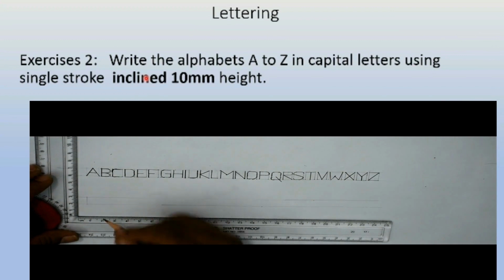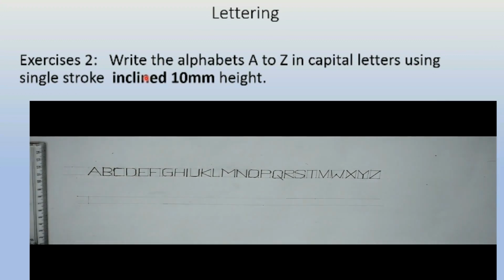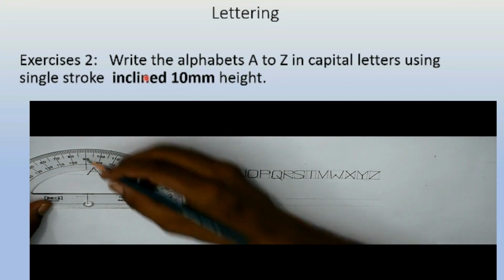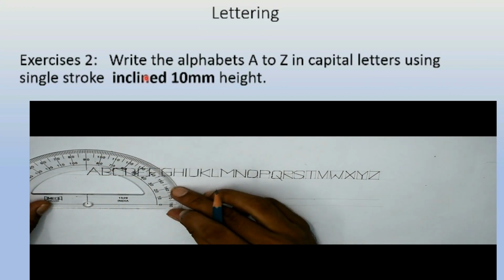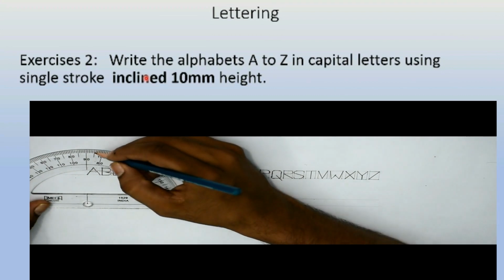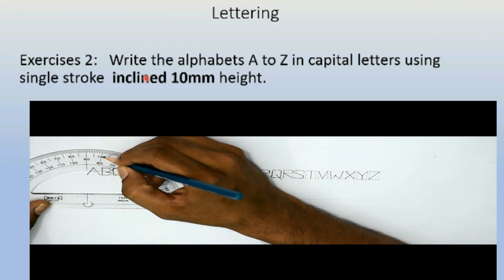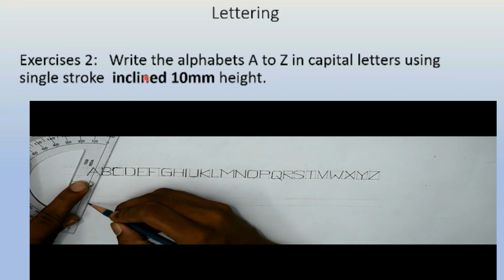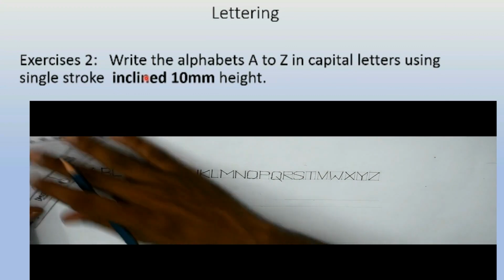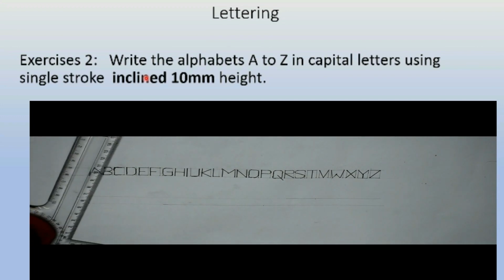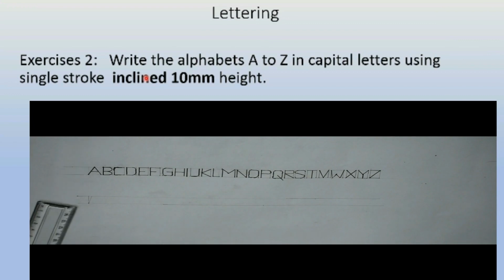Incline here with the A. But now here, these are not vertical strokes, these are inclined strokes. So we have to take an angle of 15 degrees. 15 degrees, that is from this side, or if we are taking from this zero line, this would be 75. So 15, that means between 90 and 105, this is 15. Take this first angle carefully, because we will mark the angle only once. Afterwards, we'll just set the drafter in this inclined fashion and we will take the dimensions.